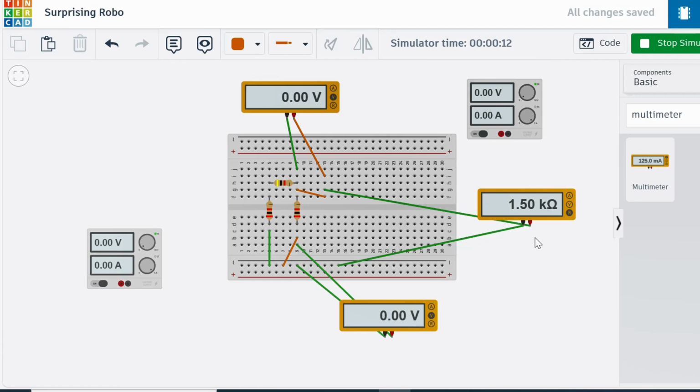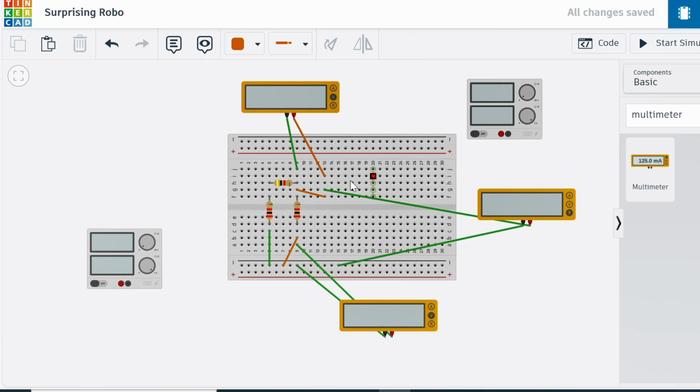Okay, so this is how we're going to measure R Thevenin and V Thevenin in the lab, given a circuit with independent sources. Now let's verify the actual voltage across the 6K. So to do this, I will just connect back the supplies. So let's remove the short circuits. The plus to this terminal, the minus here to the ground.